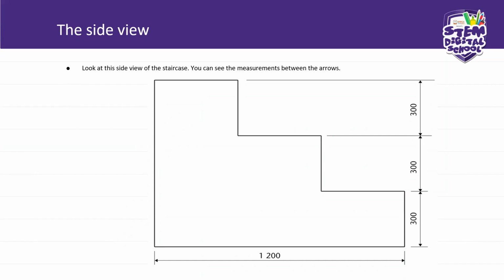When we are drawing, we don't use faint and margin paper. Shy away from using faint and margin paper because the lines on it can mislead you. Use plain photocopying paper and use a 2H pencil. Have an eraser and your pencil must be sharp.